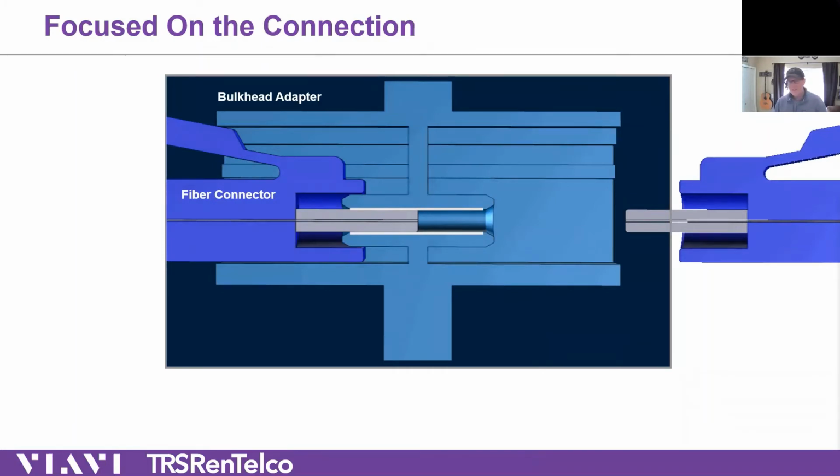And the reason for that is you're going to have minimum two connectors, one on each end, 2, 15, 10, 5, 30. You never know. It all depends on how long the network is and how old the network is, because nobody replaces the fiber. They splice it and they add new fiber to it. But core fiber underground tends to stay underground for 50 years, give or take. So if I can measure the fiber, but there's nothing I can do about it, I have to quantify that out.